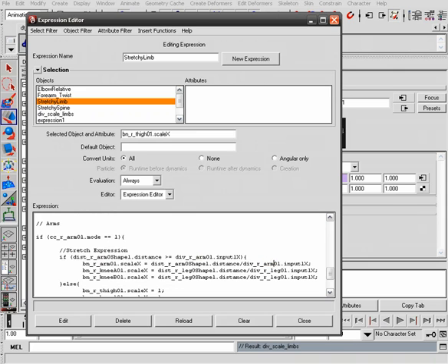And then for the next bone down, that's going to be elbow. So we want to make sure we add that. We don't need to add our elbow preserve. That's going to follow just as we need it to. So we'll make sure that we switch our expression. So again, here, our dist arm or our dist leg, that's going to also need to be switched to arm. Okay, and our leg here for the input, that's going to need to be switched to arm too.